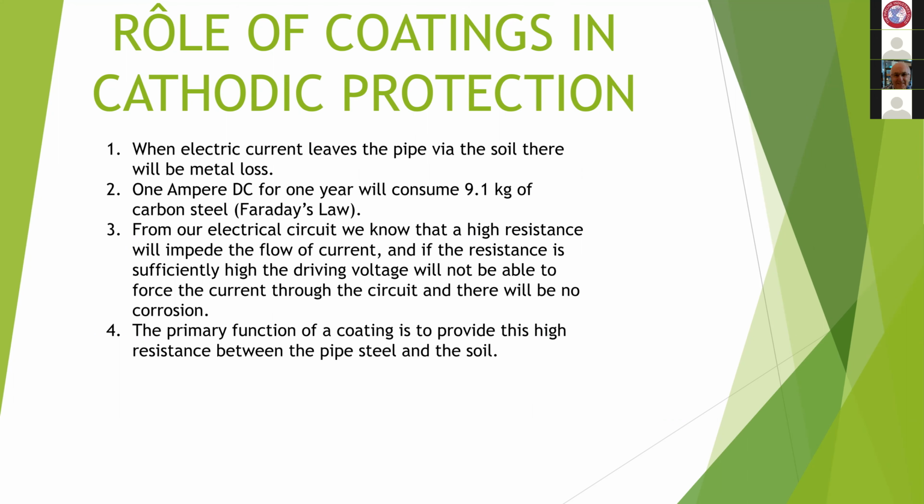So obviously, we've got to reduce those current paths that leave the pipe through the soil, because that's when we get the metal loss. And we know that if you've got things like stones in, as I mentioned earlier, they will impede that flow because they're a high resistance.